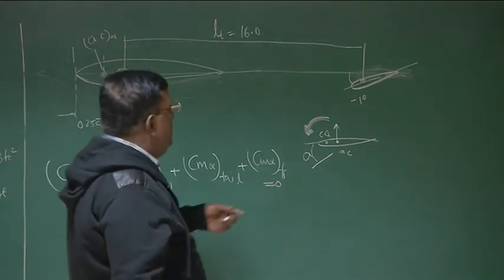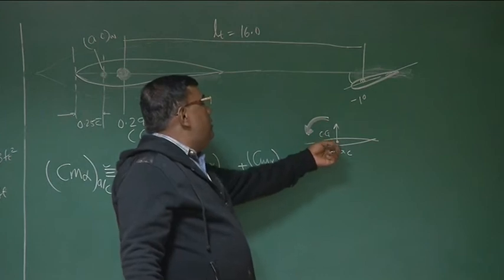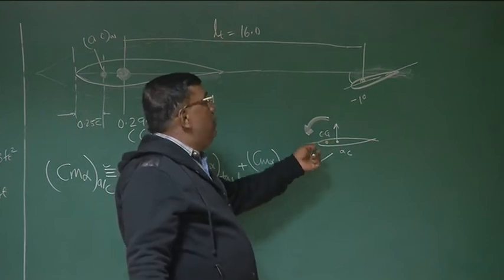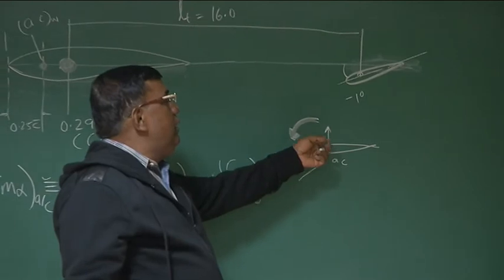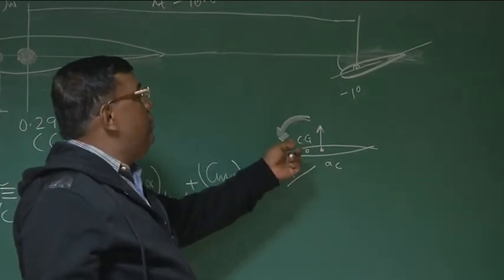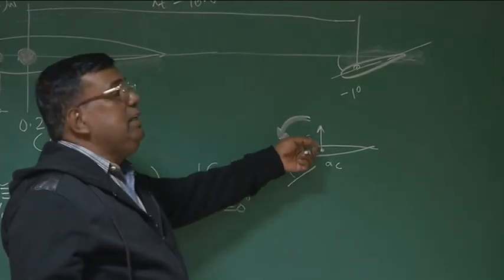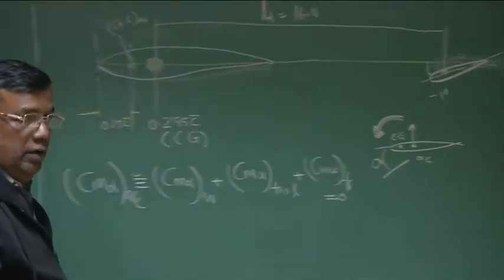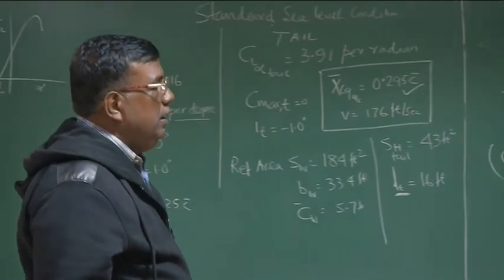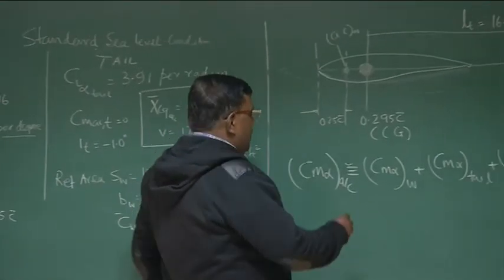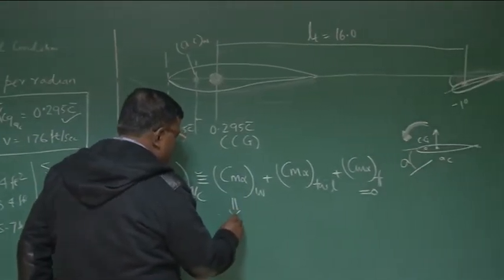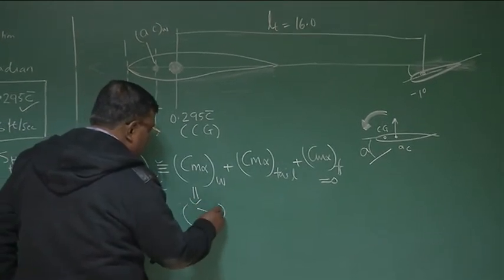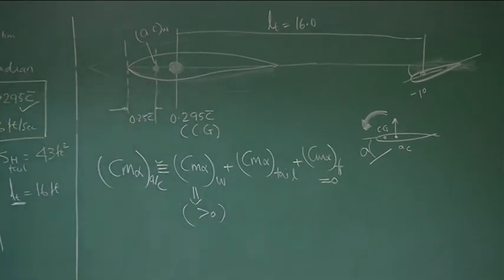Or in other terms, because the AC is behind the CG, the moment there is a disturbance it will generate this force CL, which will give a pitch down moment, so it has an initial tendency to come back to equilibrium again, that is, at alpha equal to 0 or any desired alpha, alpha star. The Cm alpha sign for the wing, you will find, should come positive, because this is destabilizing.